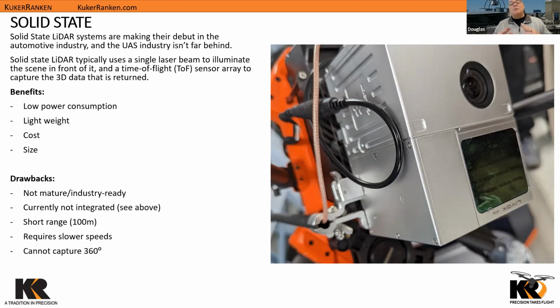And we do have some challenges with solid-state LiDAR, although those challenges are diminishing about as quickly as I'm speaking to you now. So, for example, 2 years ago, when we saw solid-state LiDAR systems being put onto automobiles, those systems could only run a very, very short range, typically about 30 meters at most. For drone work, that's just not far enough. 100 feet isn't going to get us where we need to go. However, in the course of just 6 or 8 months, we started seeing longer range solid-state LiDAR.